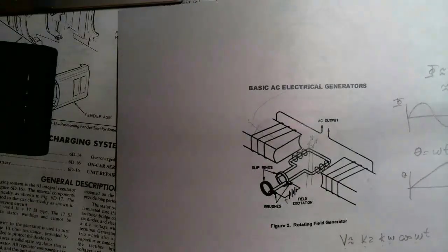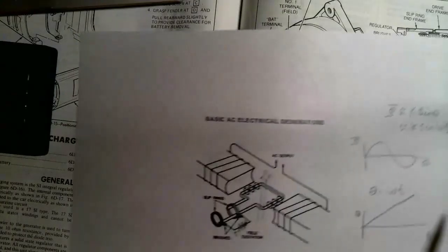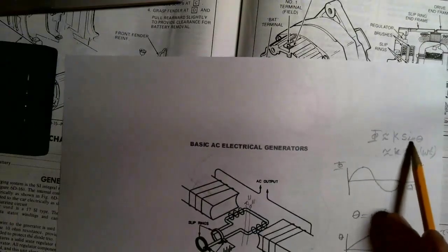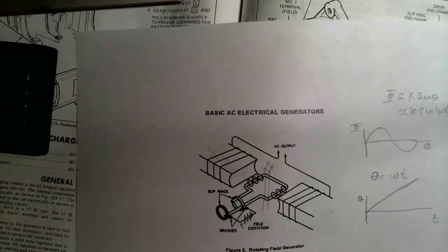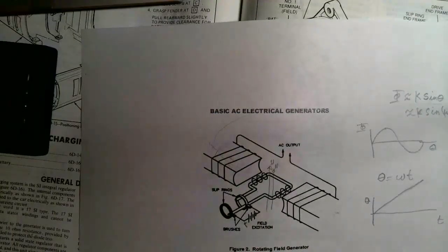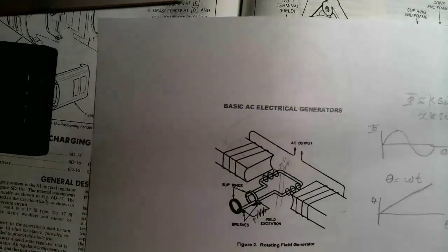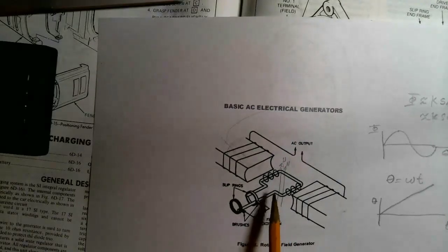So you can see here maybe that first of all you get AC, and the reason you get AC is because our flux looks like this, and then when we differentiate this, we get that. All right, and the output's proportional to omega, directly proportional to speed. Now, you know car engines run over a huge range of speed, so RPM-wise, from maybe 600 to 6,000 RPM, it's a factor of 10 at least in RPM, and then directly proportional to the current that flows in the rotor here.